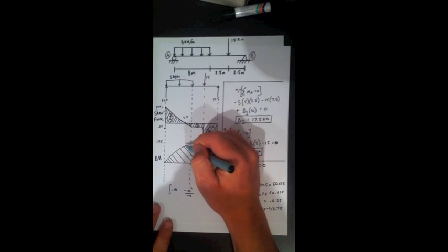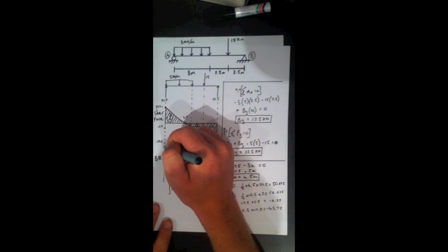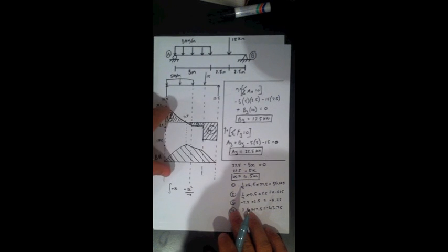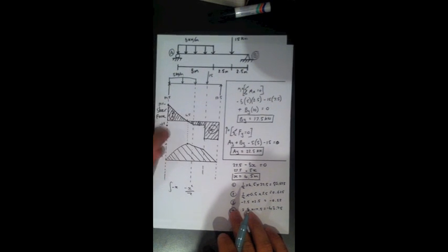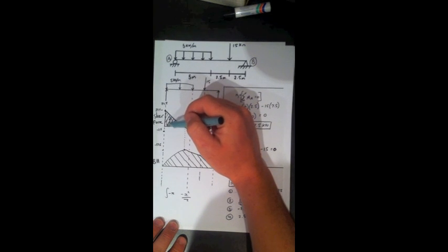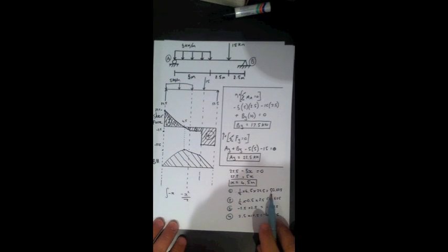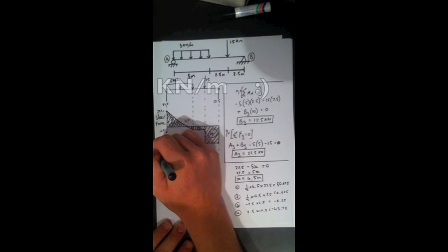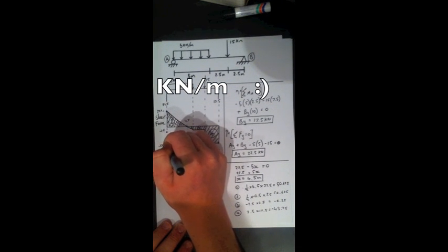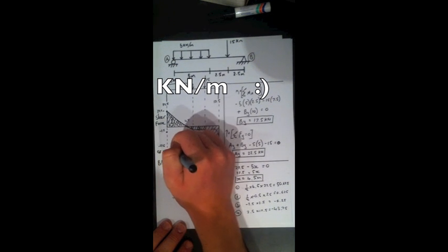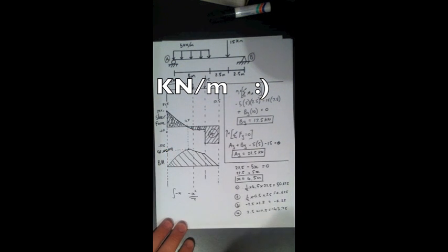So the last thing that we'll do in this is your maximum bending moment, which is at that point there. It's always good to write it into your diagram, and it's simply this. Since it's the integration of this, it is going to be the area under here, which we already calculated at 50.625 kilonewton meters, and that corresponds to our maximum bending moment on this beam.